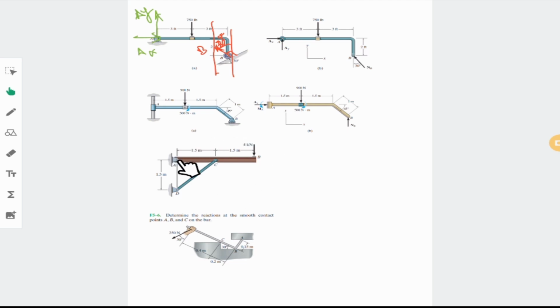And let's get to this one. This one is like this. If you consider the point A, you have 2 unknowns here, and you can get only one other unknown because you are dealing with one piece and you have 3 equations. Accordingly, this guy should be a 2 force member, meaning that it's not adding 2 variables to the unknowns, it's just adding a force here.